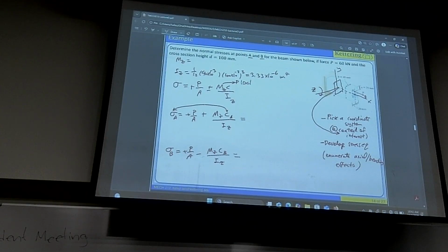Remember, we said if the bending axis is found, put these arrows, measure in those directions. So go from here to the point of interest. Go from here to A, you have to go 50 up, that is 50. So CA is 50 millimeters, and so is CB. Guys, again, it's about instruction. The person who developed these gave us these instructions. If you follow that, you will get it correctly. Jacob knows them all.